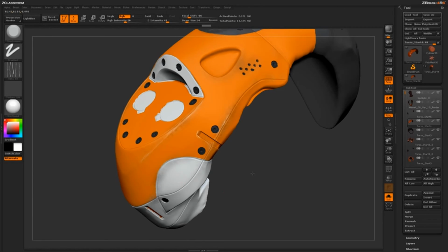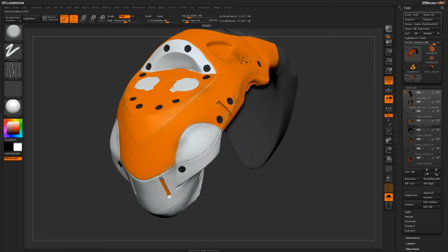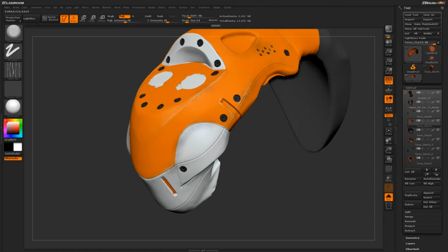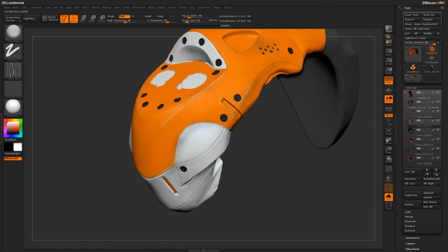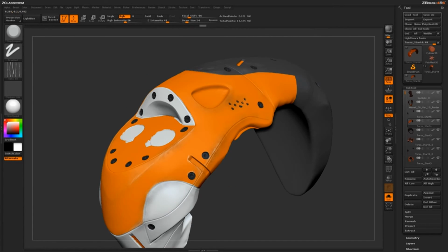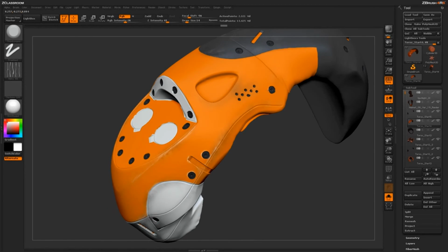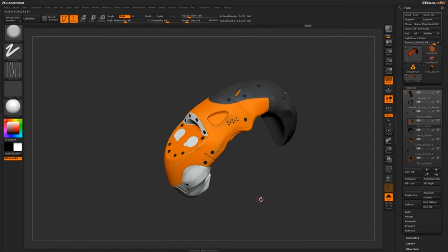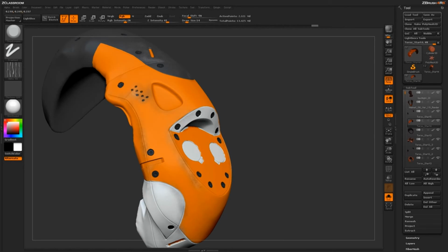You can also apply any textures to it, so you can open up your spotlight option again and paint with this brush and spotlight like we did with the standard brush. But it's pretty cool for giving just a little more edge wear along surfaces of bolts, rivets, things like that that may come on the surface of your model. Since that trim dynamic brush is using a depth masking option, you're going to see it's only going to hit those edges, which generates a pretty cool effect.